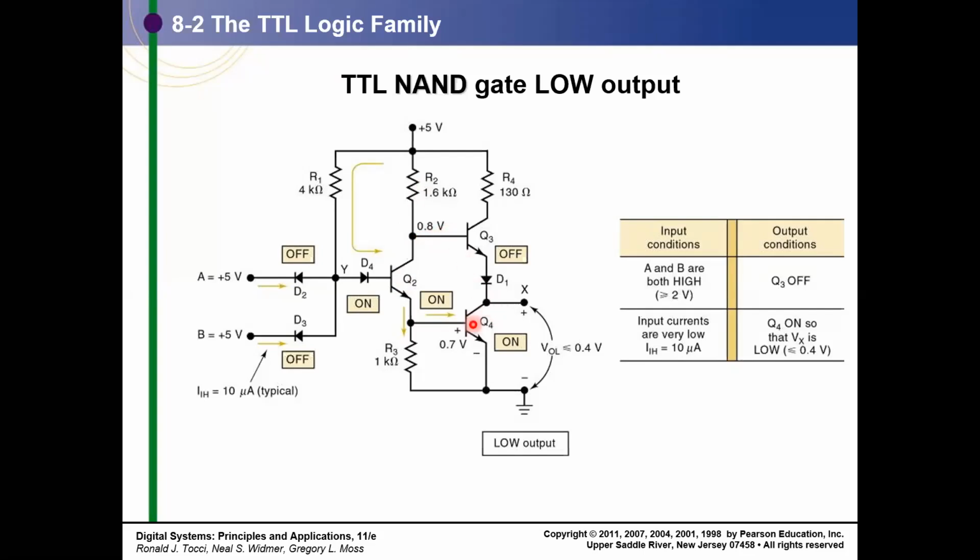Because now this is on, this turns off because this is going low, 0.2 volt. And this is another diode sitting over here, so you need 0.2 and here one diode drop, so something like 0.9, and this is 0.8, so this cannot turn on. If this cannot turn on, this is an open path, this conducts and it reaches the ground.